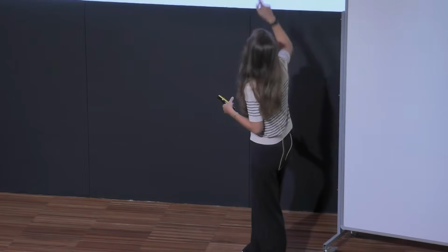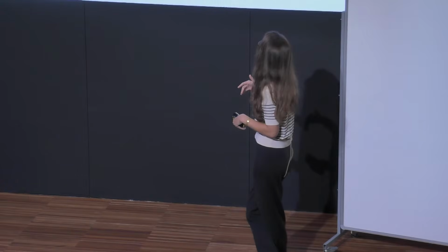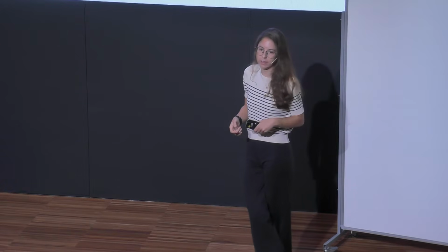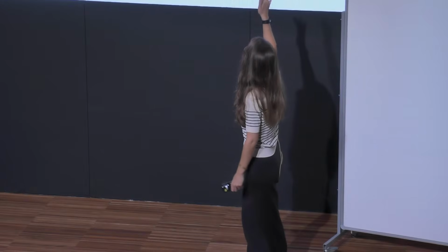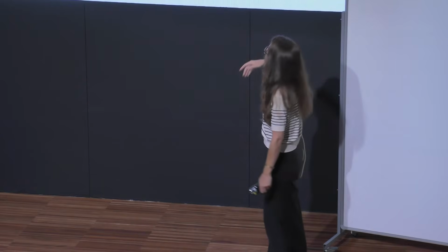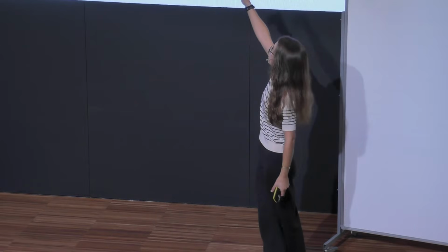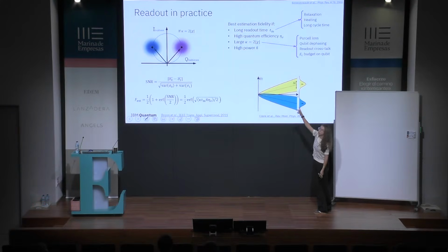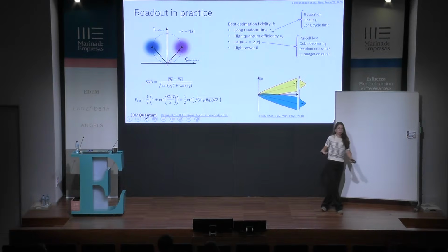And this is inversely related to the charging energy, which we said we want to keep at a reasonable level. If it's too tiny, then anharmonicity is too small, and that's a problem. So we have a minimum, or target, charging energy, so we cannot keep increasing the capacitance for chi like crazy, because otherwise it might not be compatible.